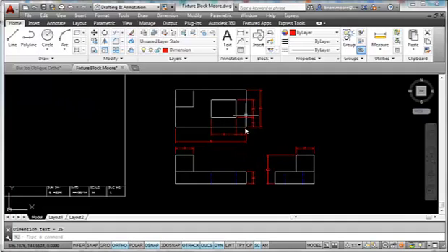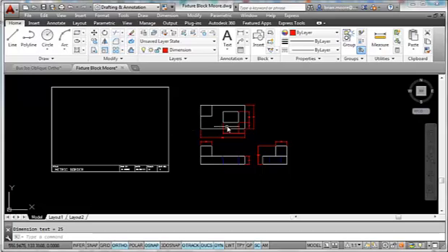When you place a dimension, you could tell it to go 10 out. However, it will work sometimes and not other times, and I can't tell you why it doesn't work sometimes. So I suggest you always use the offset method, because otherwise some of your dimensions are not going to be located correctly. So the next thing I need to do is to center this.